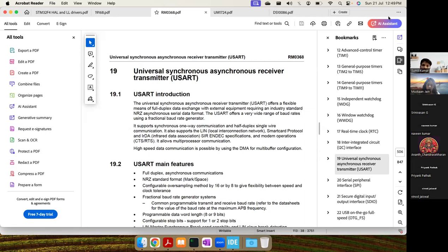Yes, the start and stop bits are just a way to enclose a packet of data. If you are sending 8 bits of data, you want to enclose it in a start and stop condition. You need to do this in asynchronous communication, because the receiver doesn't know where the data is starting and when it is ending. And in synchronous, you are right, we just use the clock and don't use the start and stop conditions.